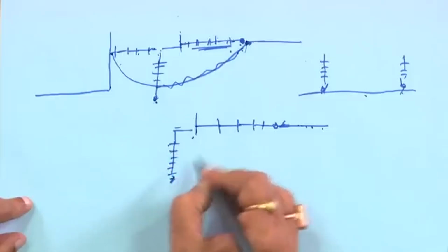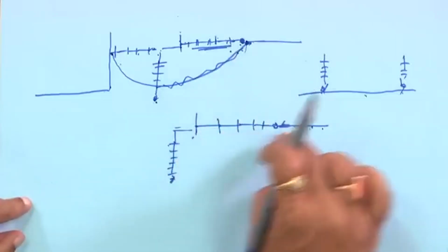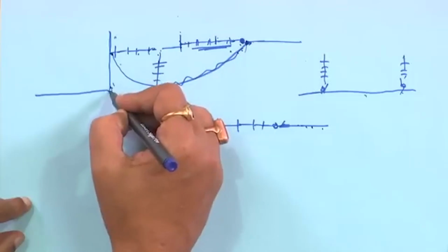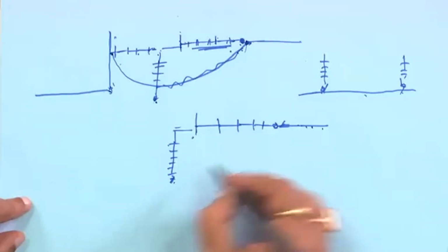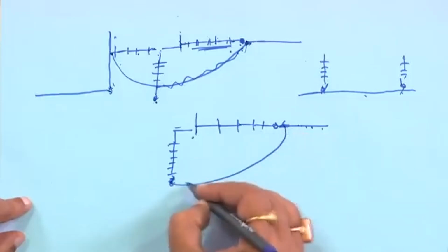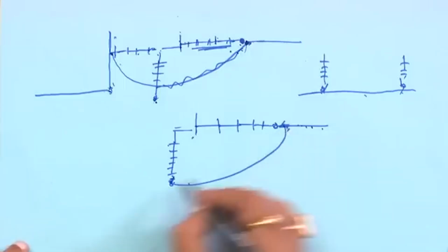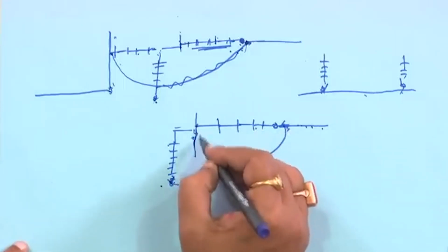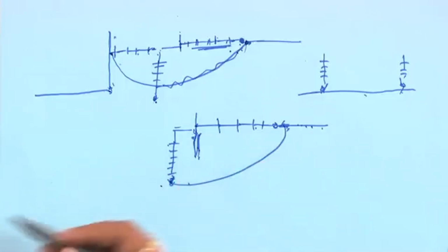When the conductor is coming from one direction and changing direction, not necessarily 90 degrees but another direction, then this portion should be connected with the conductor like this. Otherwise, how will continuity be maintained? Because this is an insulator, and there it is connected to the tower, right. So, this is how things take place.